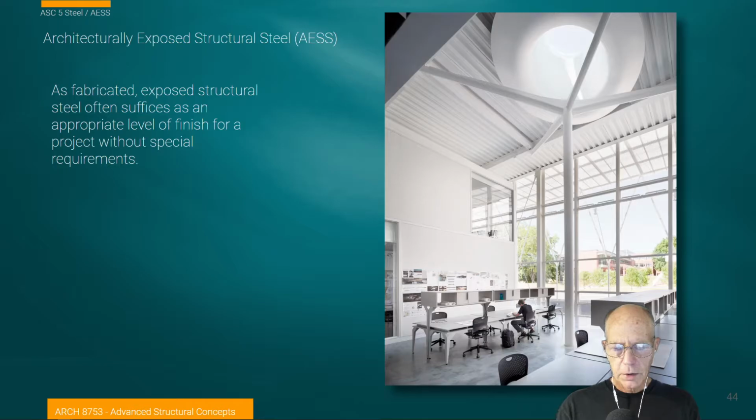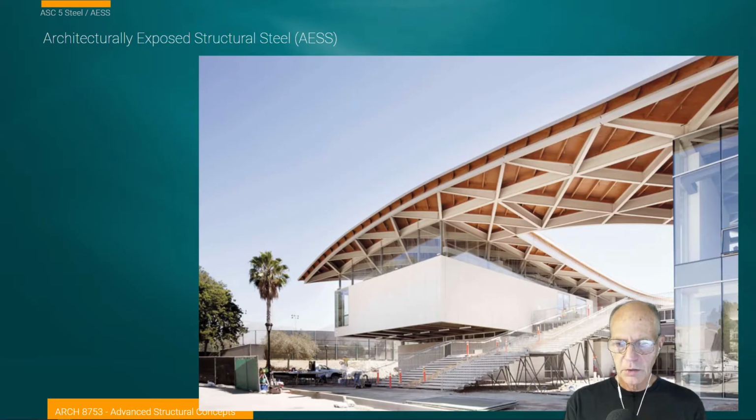Obviously a steel beam can be rusted, its coating system, if it was painted for rust resistance, could have defects in it. All of those things could be fine if they were going to be covered with fireproofing like drywall or in a ceiling cavity. But when we want to expose them, and this is the primary discussion about this, we need to be able to specify to the contractor, to the fabricator, the kind of appearances that we want. We need to be able to have a common platform for that kind of dialogue and specification.